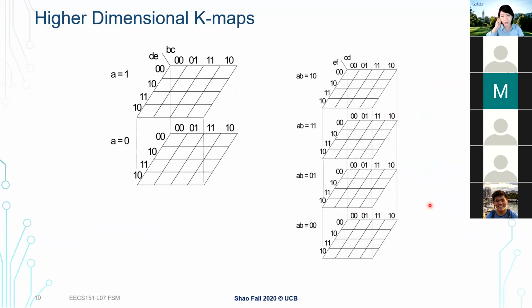And like I mentioned earlier, we can also play with higher dimensions. We can use a third dimension here to introduce either 5 variables or 6 variables in this case. Again, the Karnaugh map is all about adjacency. So we want to create adjacency so that we can see cells together where only one of the dimensions is different. In the 5-variable case, we split into a 3-dimensional table for the third variable.